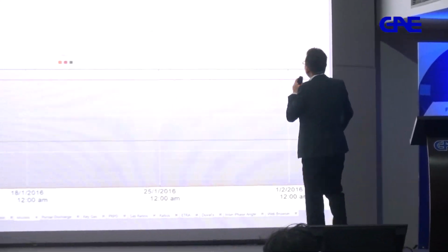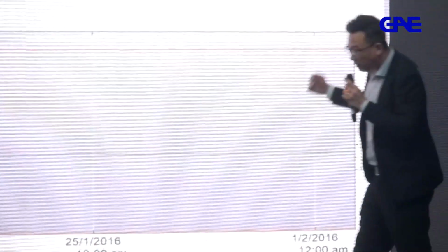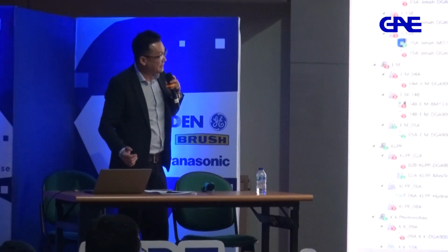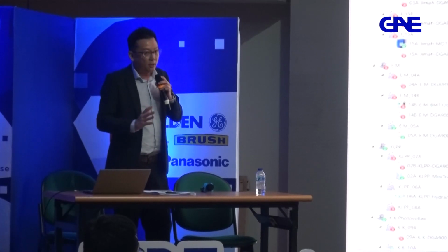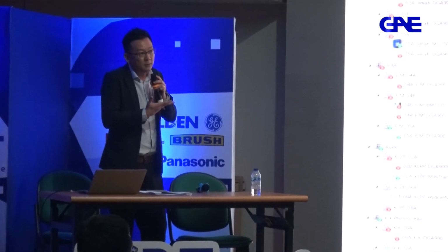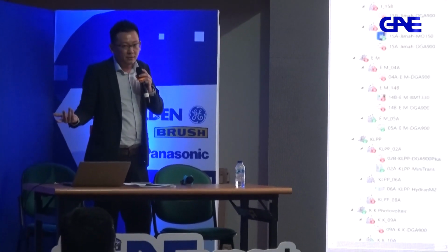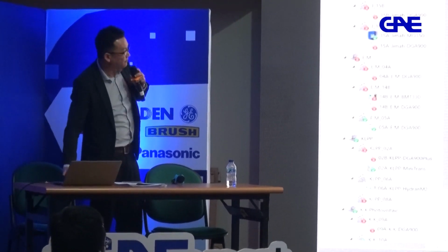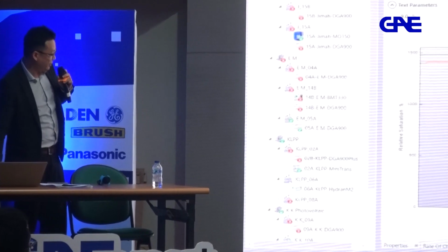Of course, OLTC motor torque, winding hotspot, all of this is inside the software, so at a glance you can monitor everything. Other than that, controlling of the OLTC is not applicable for this device. But if you need OLTC controlling, it's under another device which GE does have, our MS3000. So, yep, I hope I answered your question.